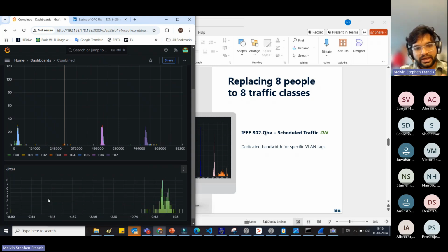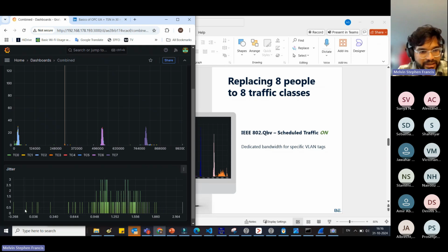Okay, and also the jitter is plus or minus 4 microseconds, and this would say that OPC UA PubSub over raw Ethernet is, so now you can see it is getting better because I started it. So it is even plus or minus 2 microseconds. So it's also in the nanosecond. Most of the packets are in the nanosecond range and some are spilling out here. So this test suite proves that our OPC UA packet is able to be delivered on time.